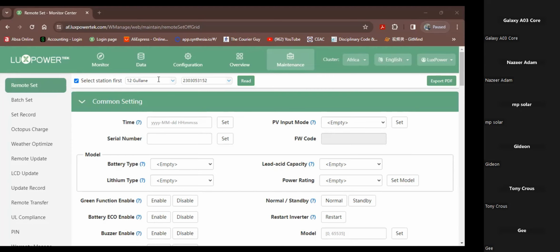So on the MPPT, we rate the maximum voltage, and then we have the operating voltage as well. You should be mindful of, and I'm going to clarify that with our sheet, don't exceed the 385 volts operating under load. The inverter is a 6.6 kilowatt MPPT, so we have 3.3 kilowatts on MPPT 1 and 3.3 kilowatts on MPPT 2. And then we have the rated current and the voltage.